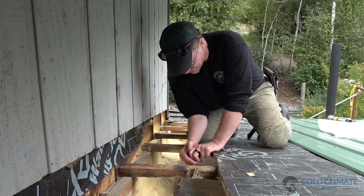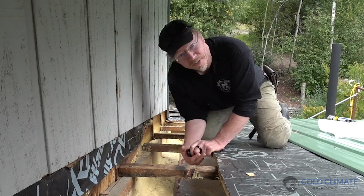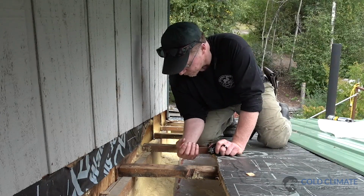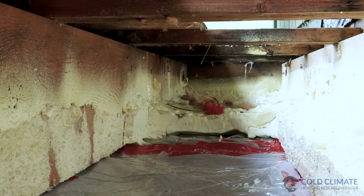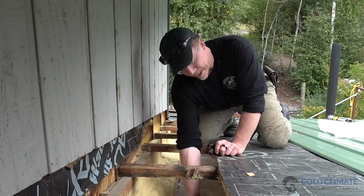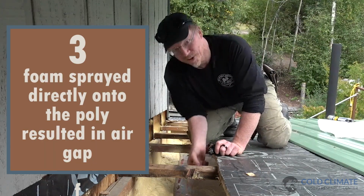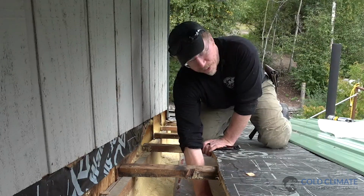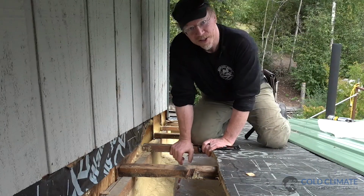The issue with some of this is that when you apply spray foam over poly, the spray foam doesn't bond to the poly. And I have had several professional spray foam installers tell me if you apply spray foam at, say, 2 inches thick, like was done here over poly, you run a risk of that foam not curing properly and possibly even separating from the poly. And that's what I'm seeing here. I have a gap between the foam and the poly that's as thick as my finger. And what that means is any air leakage through poorly sealed poly will travel around under here until it reaches a hole in the foam.